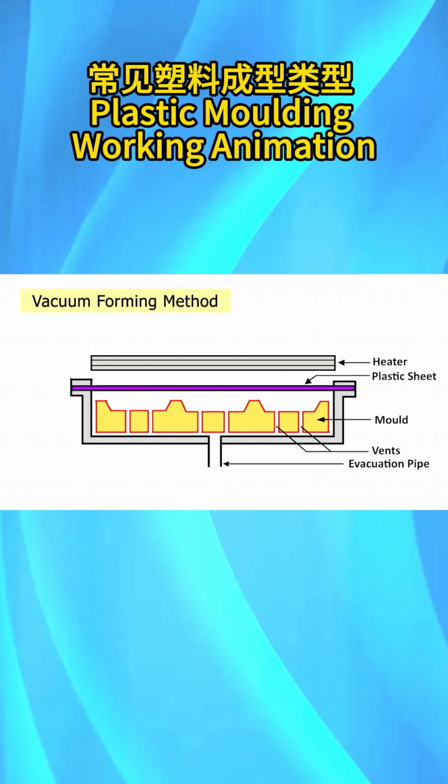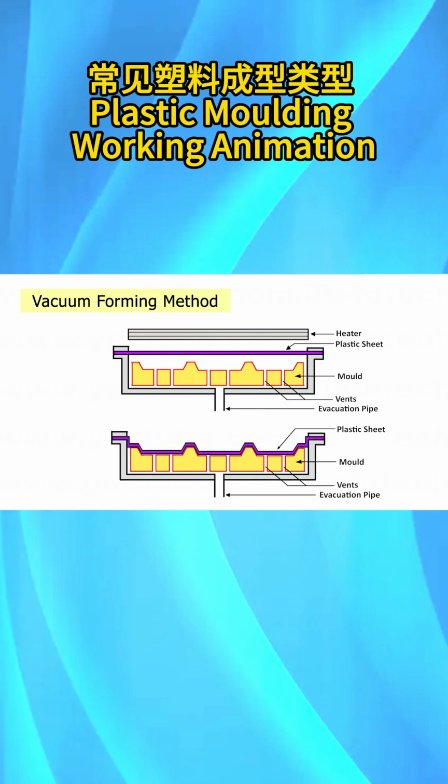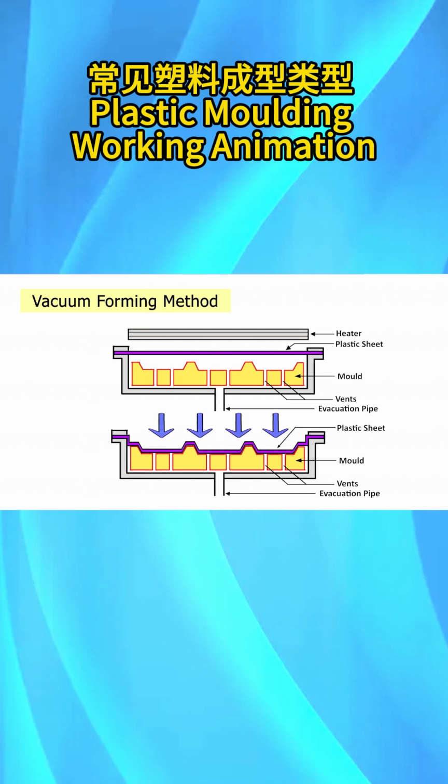In vacuum forming method, the mold is attached to a platen. The platen and mold are then lowered. The rigid thermoplastic sheet material is clamped onto an airtight gasket and usually heated from above. Once thermoplastic sheet is softened, then air is blown in to raise the sheet in slight bubble before the platen is raised, bringing the mold into contact with plastic. Here trapped air remaining between the platen and the heated plastic sheet is then evacuated by the vacuum pump. Here atmospheric pressure acting over the top surface completes the forming process by pressing plastic sheet onto the mold.